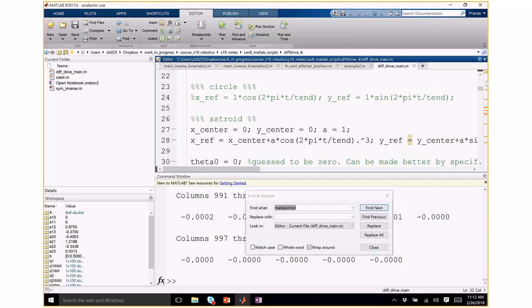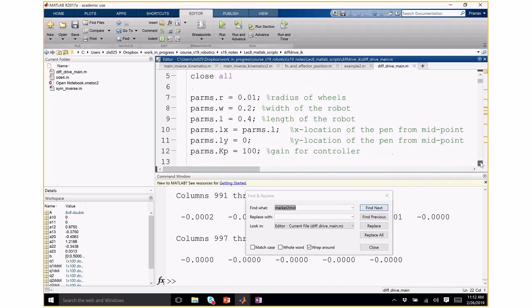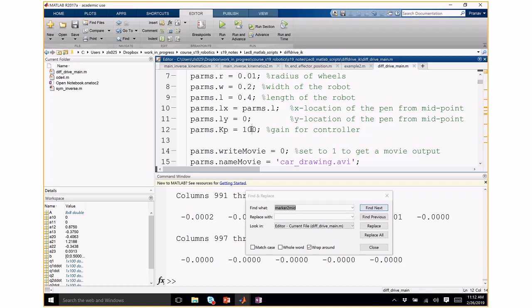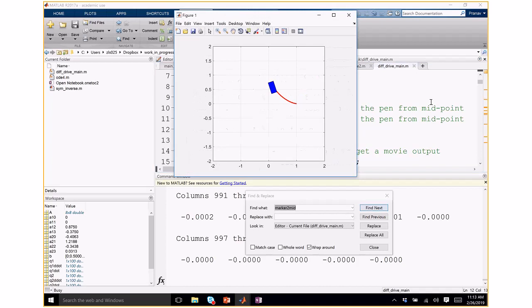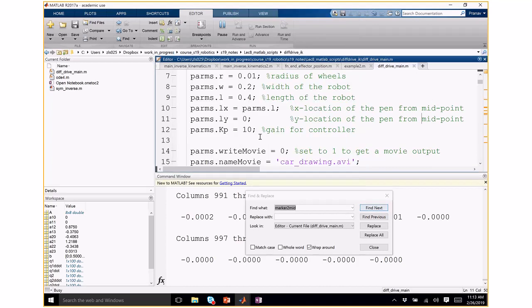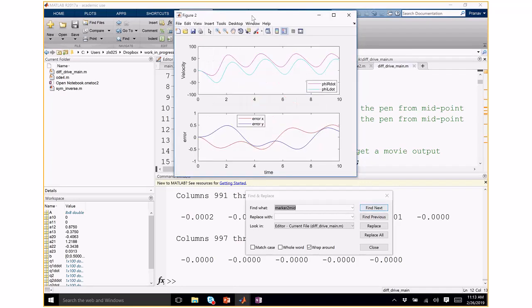The Kp, this is a user chosen thing, the Kp right in the beginning. You'll see that as you decrease Kp, you will get problems. Try 10. Oh, this looks good. That's fine. Let's try 1. If there is noise, then you'll see issues. Yeah, so it's not quite there. That doesn't even complete the curve.